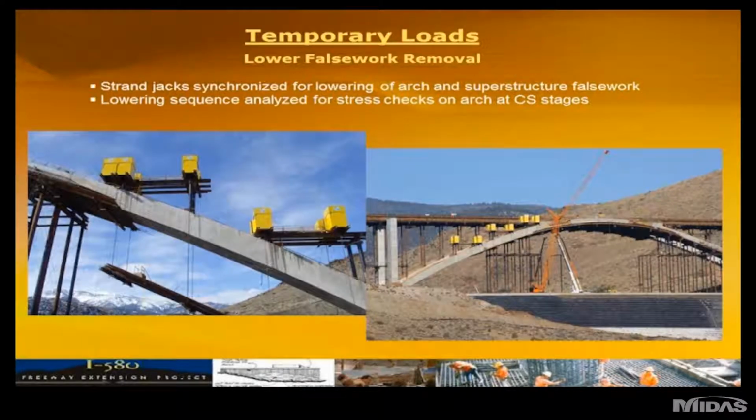Some temporary loads that were evident on the arch after completion were utilized to drop the formwork and falsework for the arch casting. So these temporary loads had to be analyzed on the structure for stress checks at the various construction stages.